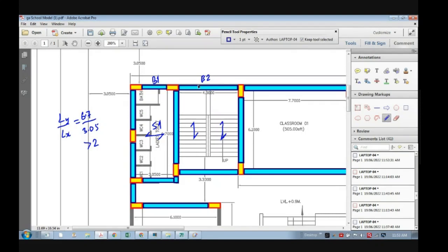What will be the level of this beam? What will be the level here in between? So whenever I start from here, suppose this is up. So all of you know that this is a half distance. So this will be the mid landing beam actually, around 3.8 or so. So I will write it as MLB, mid landing beam. Okay, so this will be the mid landing beam. So this slab flight will rest on this first. Then again from here to here it will go to the floor level.